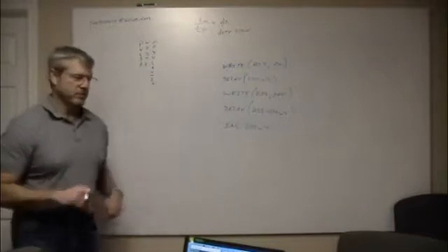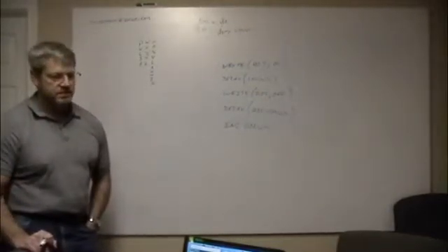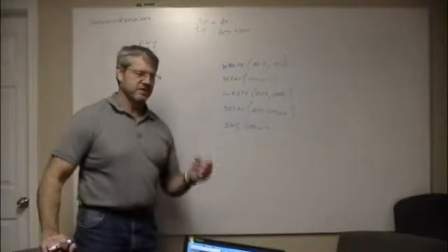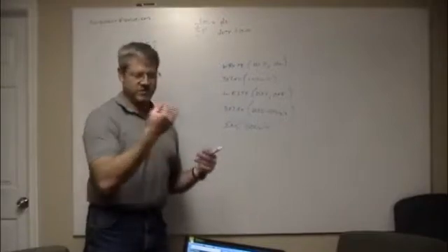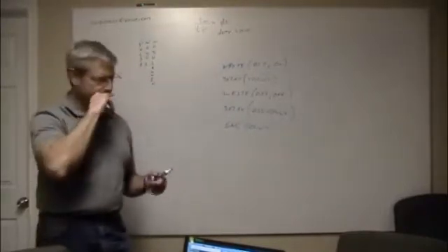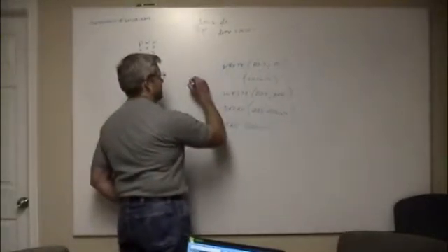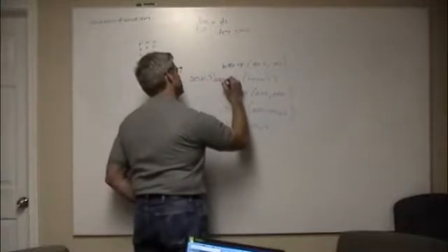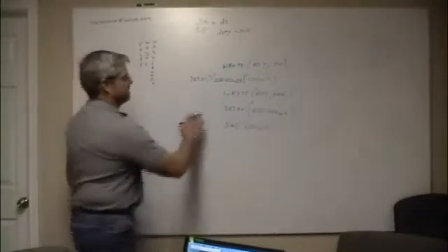Problem is the Arduino delay function is in milliseconds. And so if I turn it on for 1 millisecond and then I turn it off for a quarter second, you see this weird blinky pattern, where you can actually see it. It's too long of a time. So I did some research and the right answer was change delays to delay microseconds.